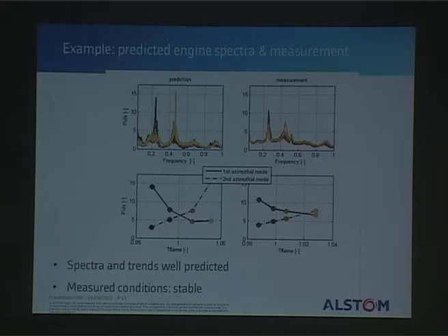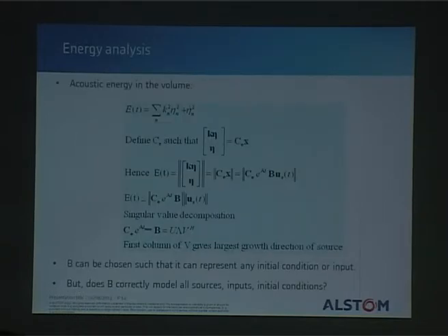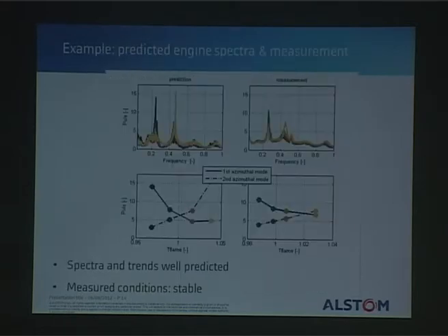And I think that's quite an important thing, because generally, of course, our products are designed to be stable, and here they are stable, and really on these borders here, it's on the verge of becoming instability. And this is typically the range where gas turbines operate. They don't generally operate at a point where it's very unstable, and also not where it's very, very stable, because there's always this trade-off that you want to reach between NOx and pulsations. You're always a bit on this edge of stability and instability.